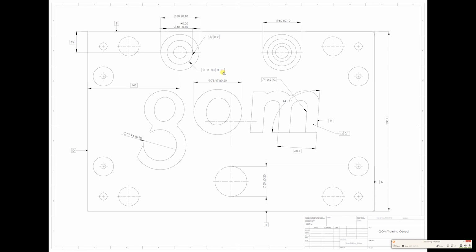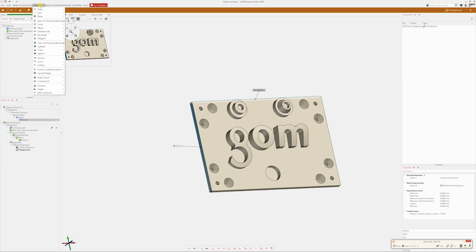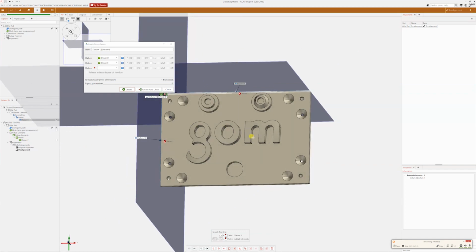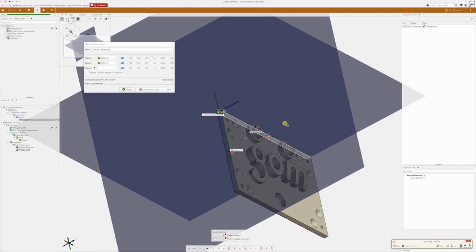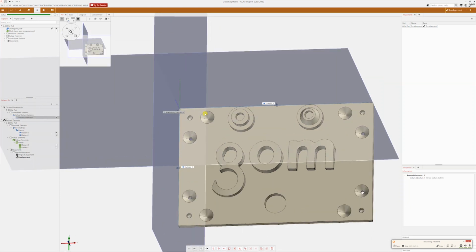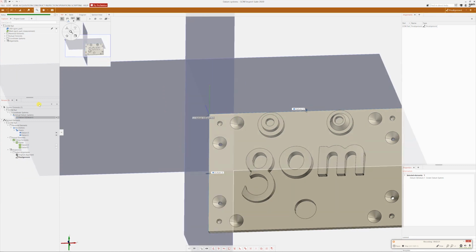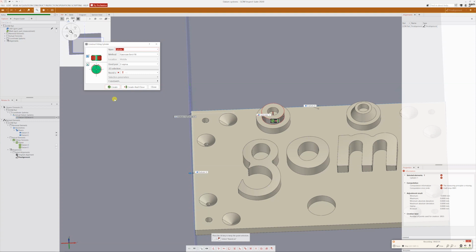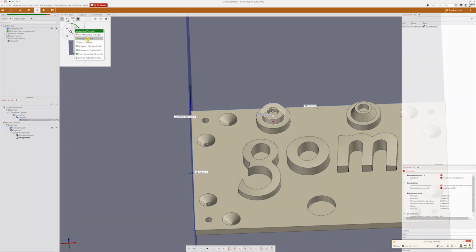Okay, so now let's try to make the two positions from here, because it's in regards to datum D and E, but I think we have to make a datum system, datum D and datum E. Yep. Okay. Yes, it's fine. Okay, good. So let's create it. We have now datum D and E, and let's construct a cylinder. Okay, create and close. Measuring principle fitting element.